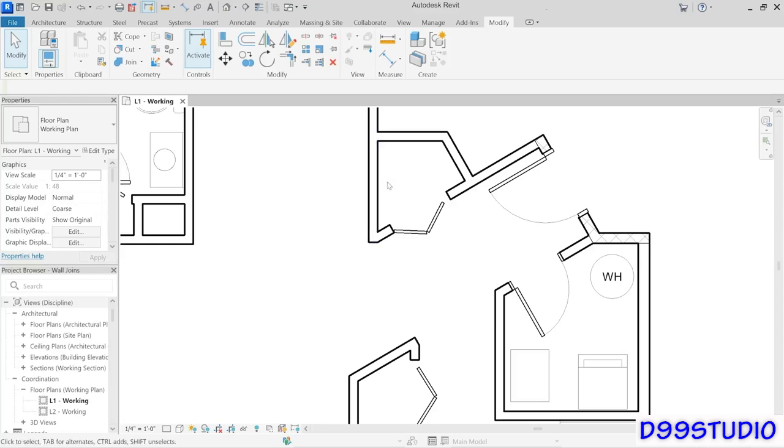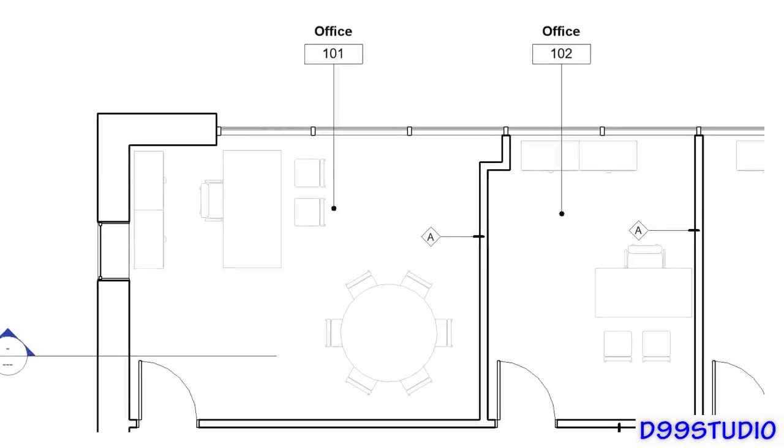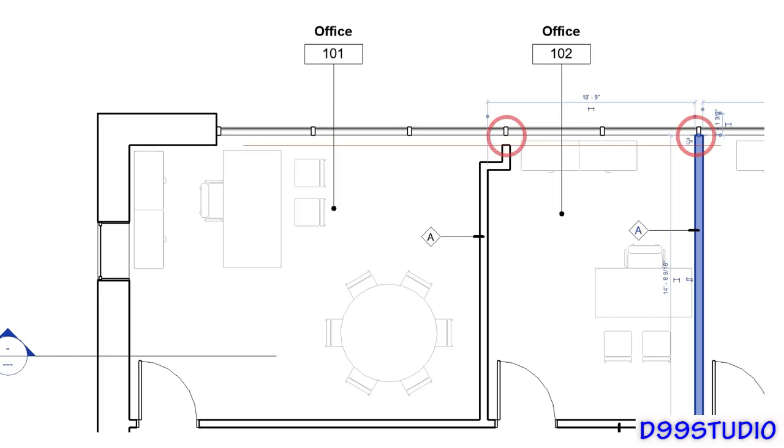So when would you use something like that? So here's a situation where it would be much more common. Here's a commercial floor plan with a curtain wall, and the default wall joins will typically try to join to where this red line is that I've drawn on top here, which means that it would look something like what you see on the left-hand side. But if you use disallow join, you can manually modify it so that the wall butts into the mullion instead of the wall itself and get the proper condition. So that's a more common example of when you would use that disallow join.